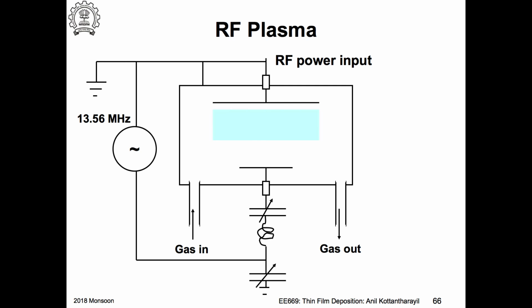So if I'm actually going to use some chlorosilane, chlorine will be produced in the reaction, and that may actually react with the metal used for constructing the reactor chamber, corrosion. So as a schematic it looks the same, but in the construction the details will differ because of the kind of stuff that we will use.